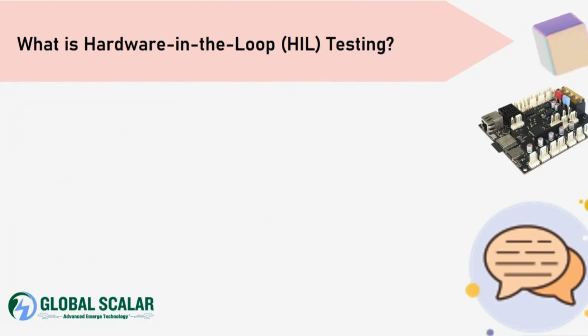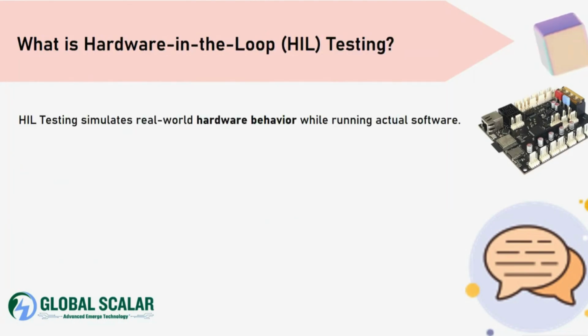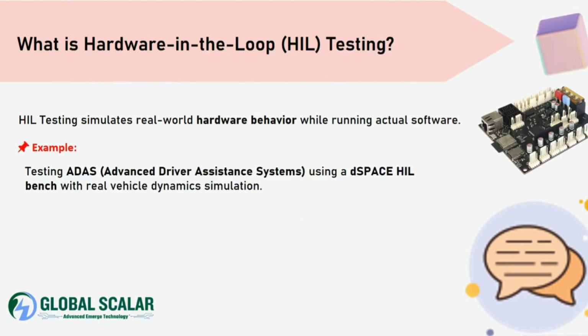What is hardware in loop testing? HIL testing simulates real world hardware behavior while running the actual software. An example is testing the ADAS using a dSPACE HIL bench with real vehicle dynamics. And the tools used here: dSPACE, NI, and Vector CANoe.